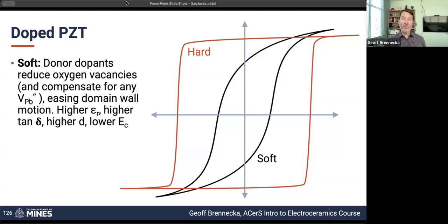So you'll also end up with different default grain sizes in each of these and different sintering kinetics. And so tuning that to your specific material and your specific application and everything else is another opportunity to tweak those. But just keep in mind that every time you're doping the material, you're not just changing the behavior at room temperature, you're also changing the sintering behavior, or at least have the potential for changing the sintering behavior, because you're messing around with the defect concentrations.